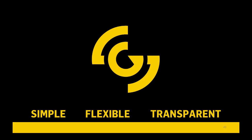So I guess, if you follow the 200-foot tracking radius, that's going to be at 30 feet. So 30 feet high, we're going to start tracking somewhere around 200, which is where I'd like to put it. But depending on the geometry and the intersection itself, you may get beyond that 200. But I know for 100%, you're going to get solid tracking at 200 feet. So that's where I like to start. So you can kind of gauge that, for every foot of height, you're going to get 8 or 9 feet of distance. But beyond really 35 and 40 feet, that's going to start breaking down. You're not going to get 400 feet of tracking with a fisheye. The resolution just doesn't allow for that. And that's when you would want to use the advanced camera anyway, to get good advanced detection further out.